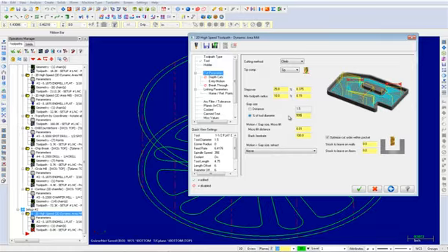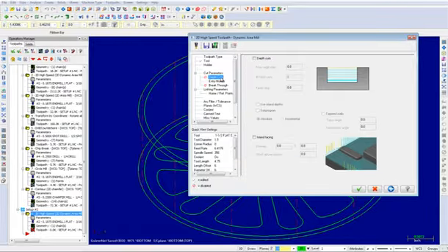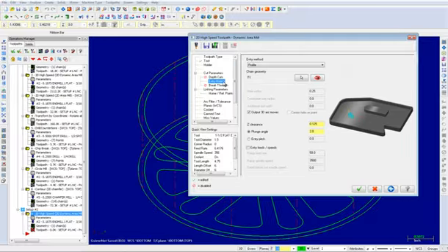Once the parameter has been adjusted, select Depth Cuts. Ensure that Depth Cuts is disabled. Now select the entry motion. Set the entry method to helix only. Also, set the helix radius to 1 and the rest of the parameters as shown.